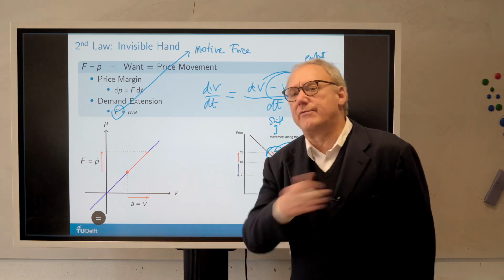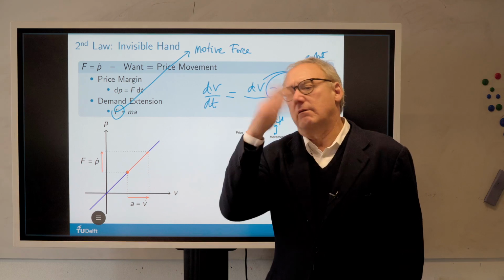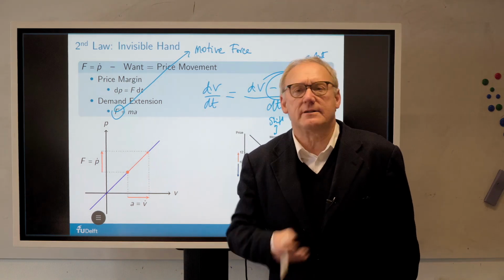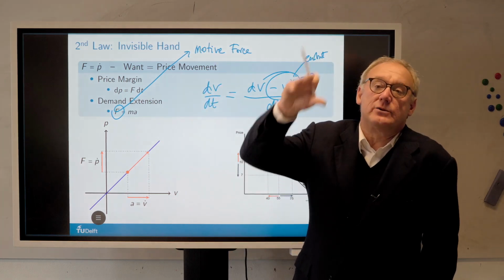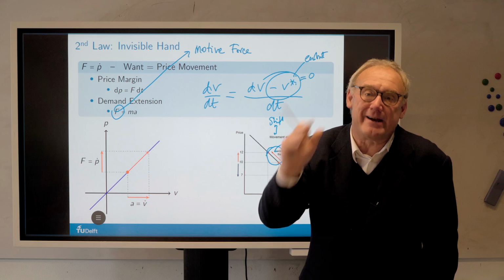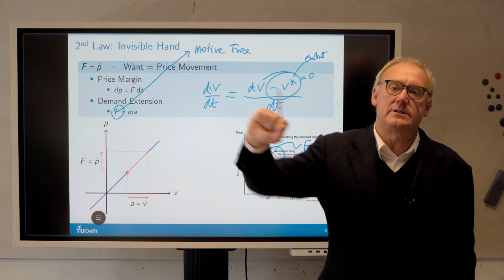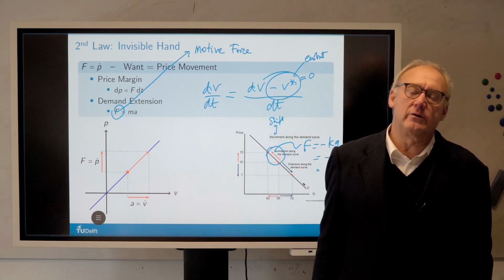In general, a voltage is not an EMF, an electromotive force. It's just a voltage drop over a capacitor. It's nothing to do with motive force. But once that is applied to an inductor, it becomes the EMF of Maxwell. It motivates this inductor to change the current going through it.